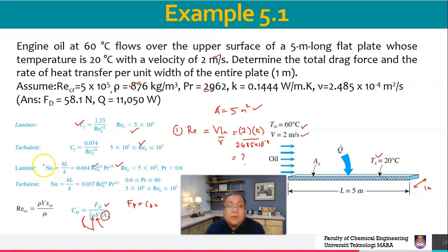Once you have the value of Nu, you will know the value of that particular h. Once you know the value of h, you will know the value of q, by q equals h As delta T, which is Ts minus T infinity.